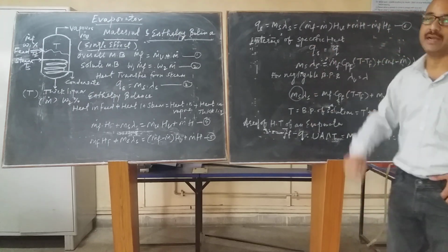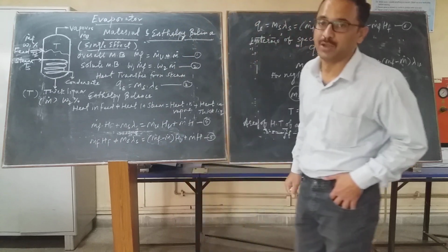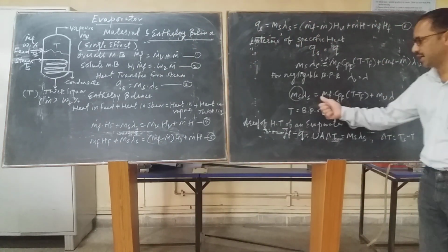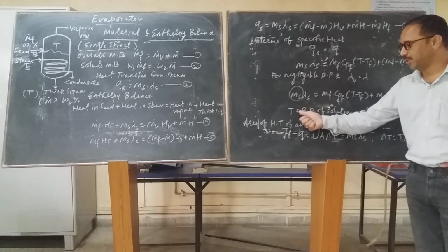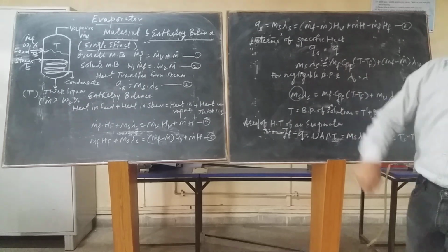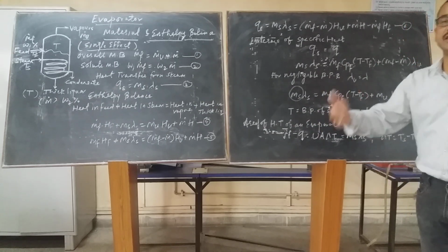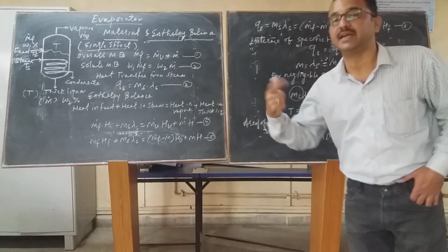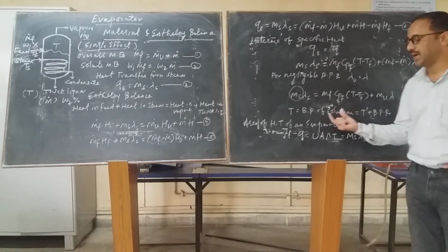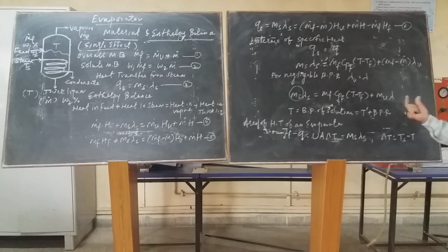Generally, the single effect shows less performance in terms of economy, just because of the boiling point rise. The boiling point rise of the solution is because of the impurities added into the solution. The solution will not boil at the normal boiling point, but at a certain elevated temperature. The difference between the boiling point of the solution and the boiling point of pure water, the pure solvent, is nothing but the boiling point rise.